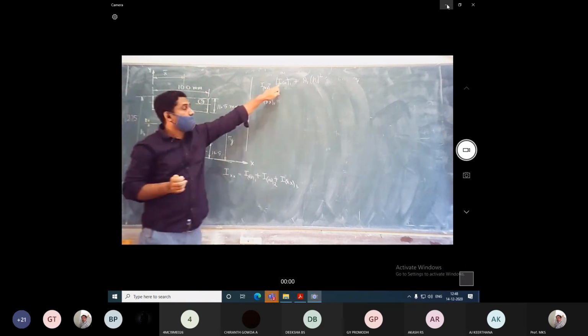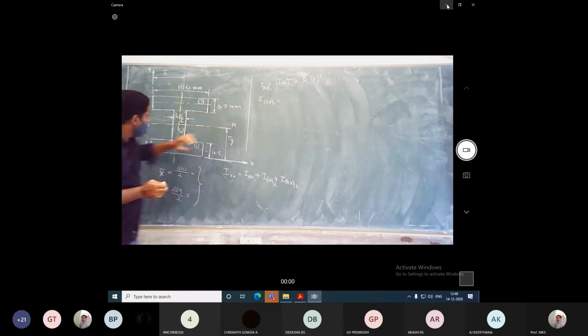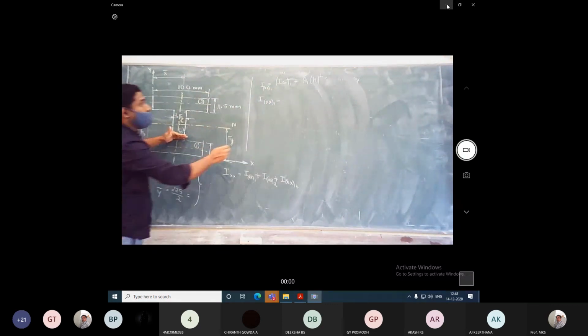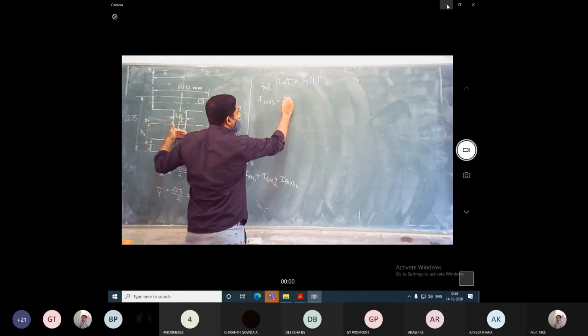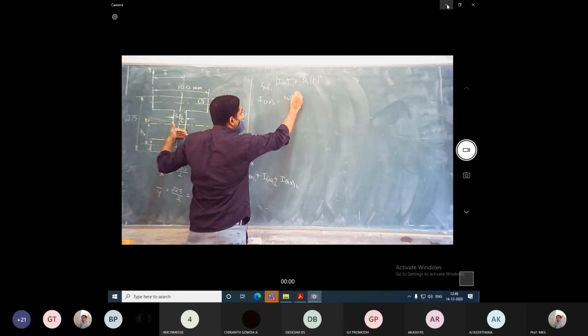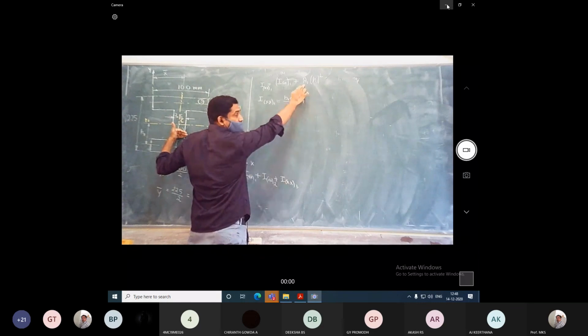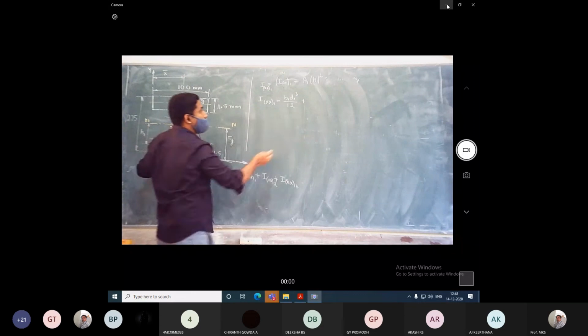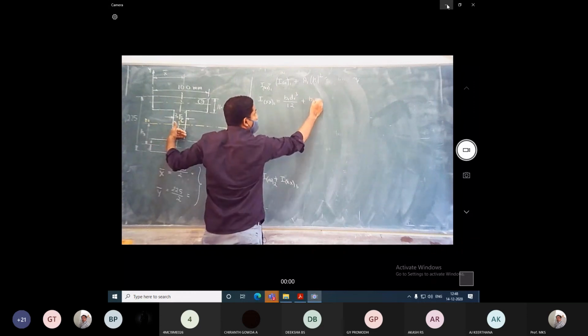Ix1 is how much you calculate. So Ig1 is the moment of inertia for only this section. It is bd cube by 12, that is b1 d1 cube by 12. The area of this section is A1, the area of the rectangle: width into depth. The width is 100 and the depth is 11.5. So b1 into d1 is the area.